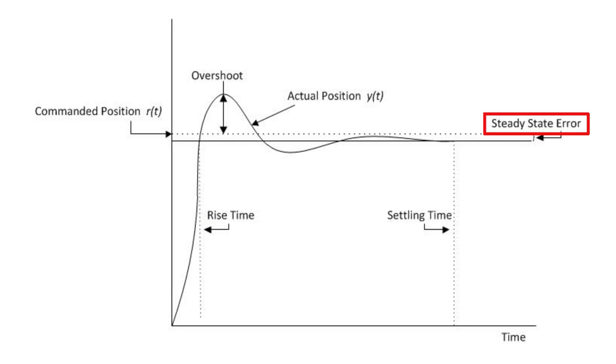We also want to minimize the steady state error, which is the difference between commanded and actual position once the motor is at rest. Ideally, your steady state error should be zero. We also want to minimize oscillation. The motor should not oscillate too rapidly or drastically because this can often damage the mechanics in most systems. You can minimize oscillations by adding Kd.